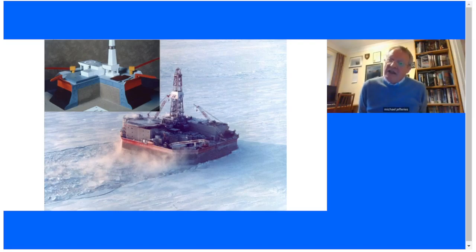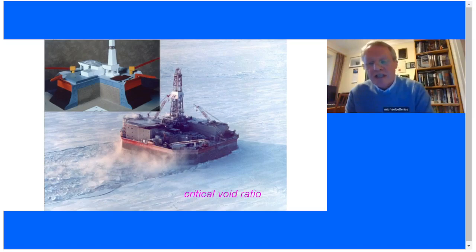And I'm sitting here as engineer of record. I'm using hydraulically placed sand. I'm well aware of this history of hydraulically placed dams failing. I know all about the vulnerability to cyclic loading. And I am just one paranoid engineer. So what am I going to do? The answer is I follow Colonel Lyman's, or the Corps' lead. I'm going to condition my decisions on whether it's safe to drop the platform onto the berm, whether it was safe to operate in winter, or whether we need to compact, based on the critical void ratio.